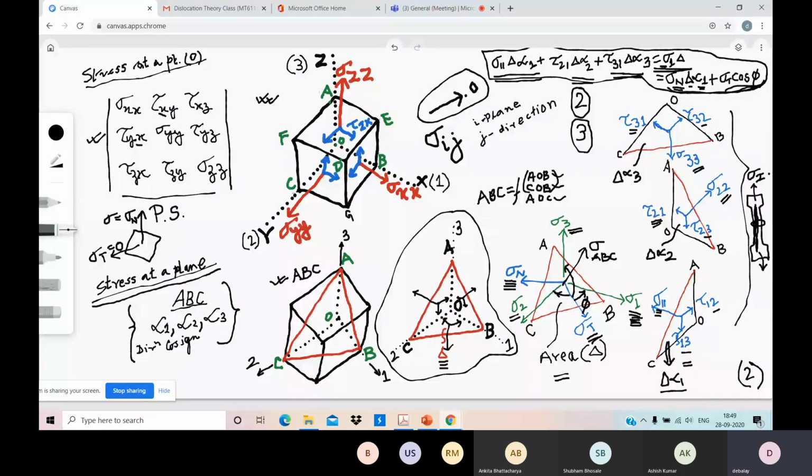So in uniaxial tensile loading, there is one principal stress, sigma Roman 1, and there are two other principal stresses acting on the longitudinal planes. If you take two perpendicular longitudinal planes, we write them as sigma 2 and sigma 3. Those are also principal planes on which there is no shear stress, and the normal stress on those planes is also 0.